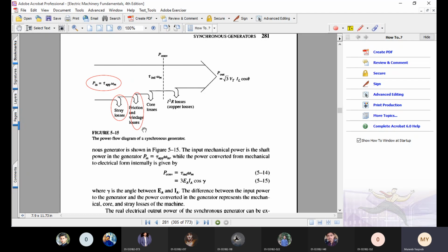Now consider that the rotor is rotating and it has a DC supply, so its magnetic field becomes a rotational magnetic field. This rotational magnetic field causes eddy and hysteresis loss to occur in the stator of the generator due to relative motion between the rotating rotor's magnetic field and the stationary winding of the stator.